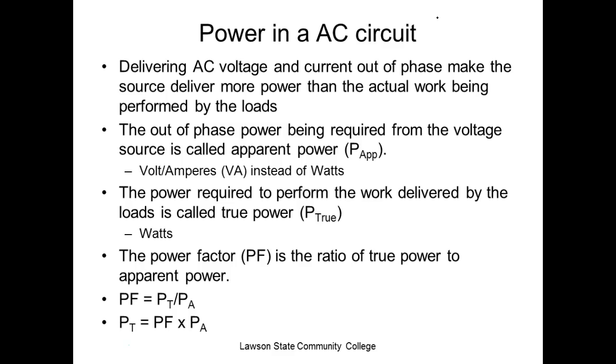So now motors have to give their efficiency. They didn't used to have to do that. They have to give the power factor rating of the motor. That's the new stuff that they have to put on motors, and we'll look at that a little more.